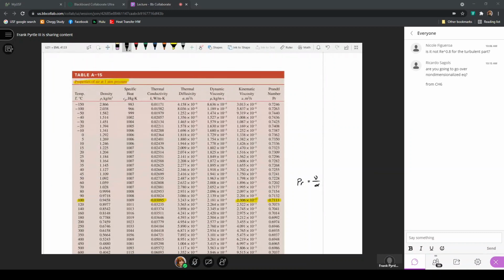For Prandtl numbers less than, well, actually, I think it's about 0.1, I don't recall, but this expression of the Prandtl number is a ratio. So really high numbers, it just says it's going to diffuse momentum better than it does heat or thermal energy. And for lower values, it says that fluid comparatively will dissipate thermal energy much better than it does momentum.